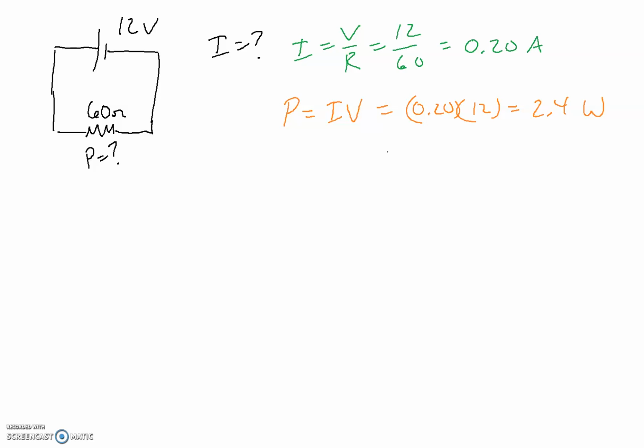This is a lot of what basic calculations are like in circuitry: simple little formulas, finding one quantity after the other and piecing things together. We could even go a little further. Let's say it was used for 80 seconds. How much charge was used? This goes back to the definition of current, which is charge divided by time.